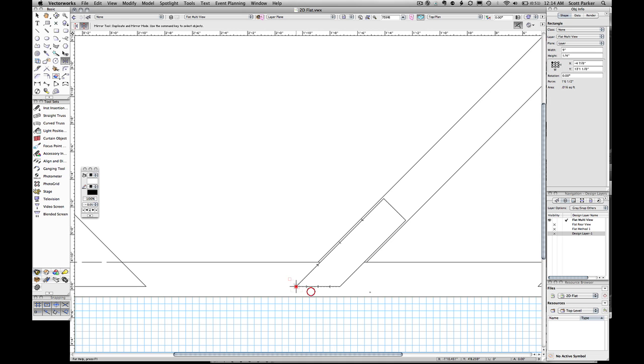Make a rectangle. There's one side. Oh, we're still in mirror mode. So I'm going to hit delete. Go up here and grab the rectangle. Click that end to start our rectangle. Click on this to grab a marker. Tab twice. I'm going to type in -0.25 for the thickness. Click on that, and there's the object. Now what I can do is grab it and simply drag it straight up.